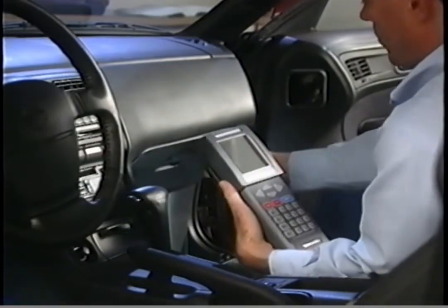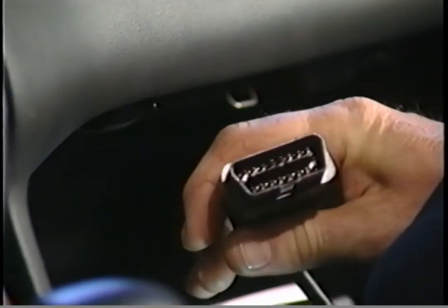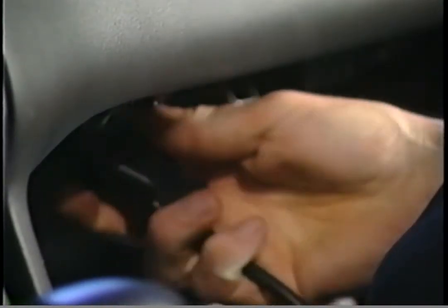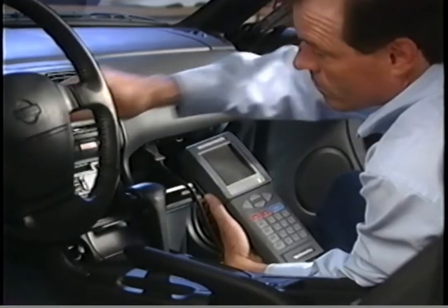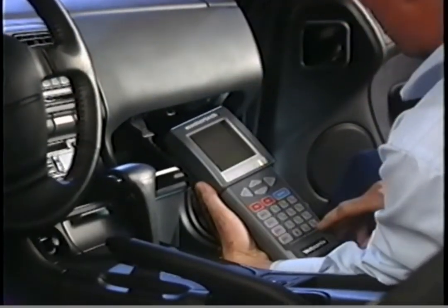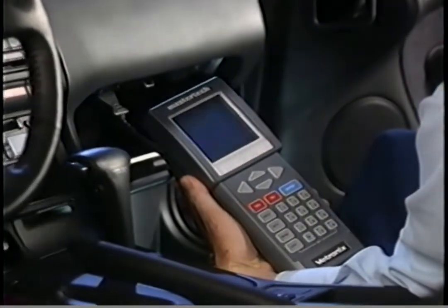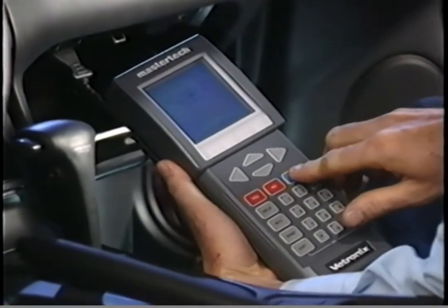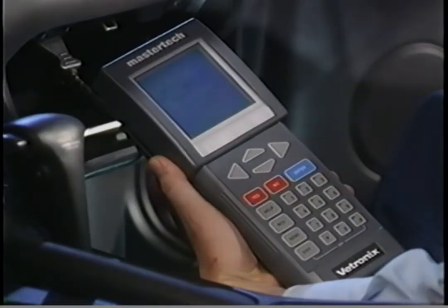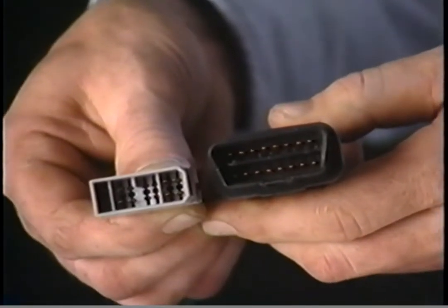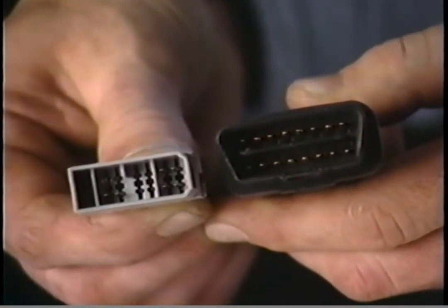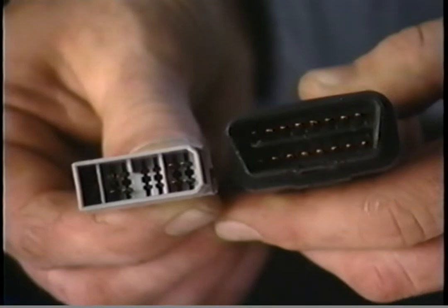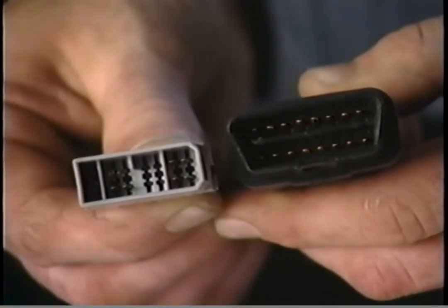A part of the OBD-II regulation requires the availability of generic scan tools, or GSTs. The GST connects to the vehicle with a standard connector, which will be fitted to all vehicles that satisfy OBD-II requirements. Nissan vehicles which satisfy OBD-II will have both the Consult and the GST connectors. Each of these connectors is unique, and the GST will not connect to the Consult connector, and Consult will not connect to the GST connector.